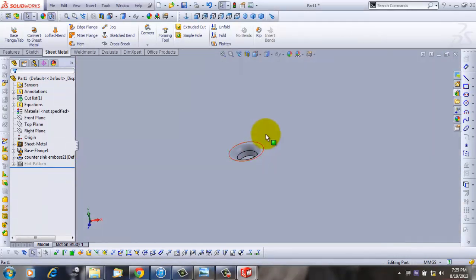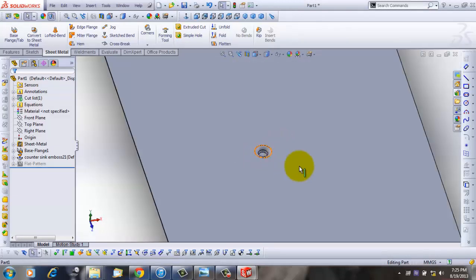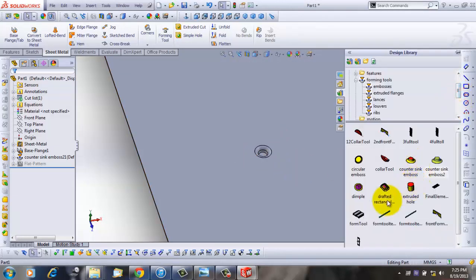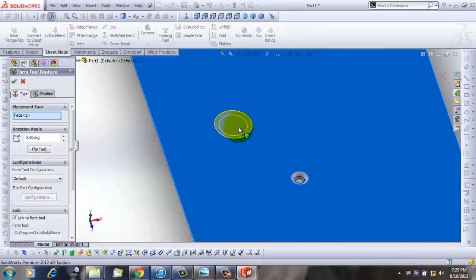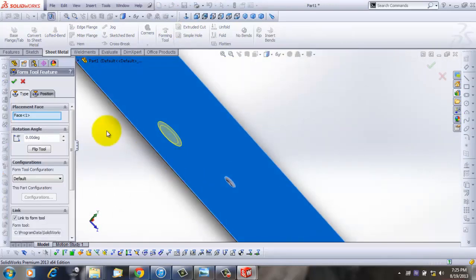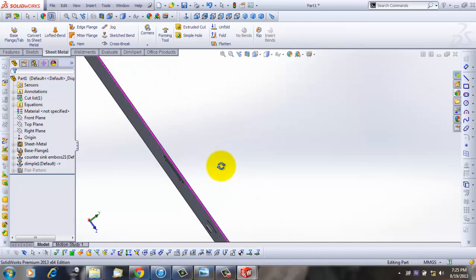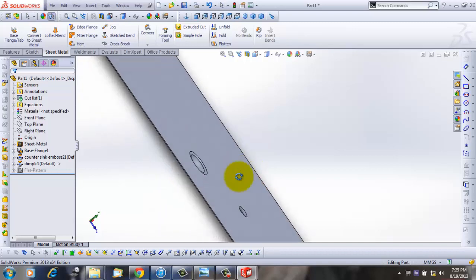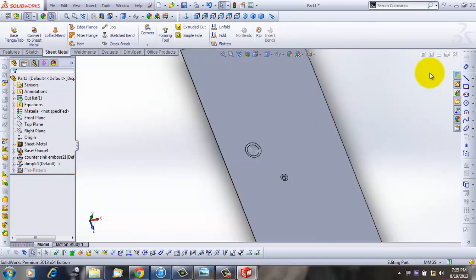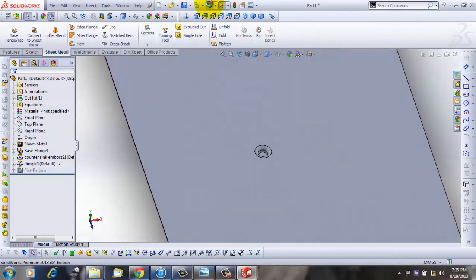Similarly, my process of making the element will be the same. There may be other processes, but I chose this one because I thought it was the most time-saving process. So I just make another emboss on this. There's a dimple emboss. The contour is very fine, unlike the other one. It doesn't have those sharp edges. And I'm just going to roll back to my sheet.